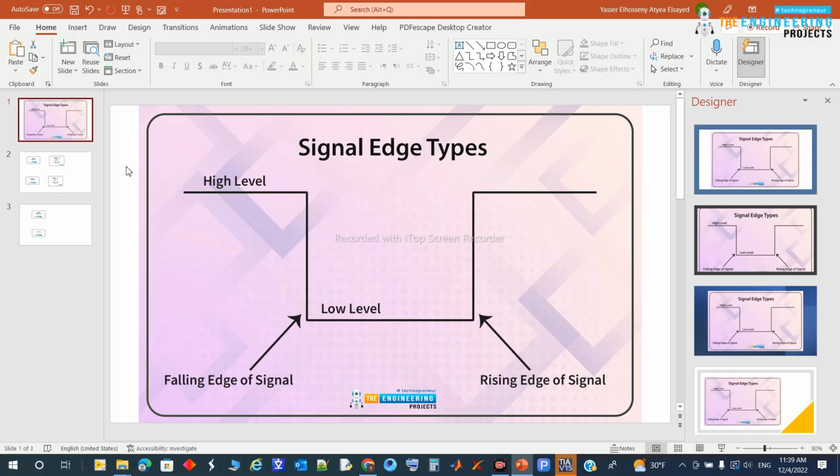Above 100 centimeters it will stop the pump, and before 100 centimeters it will start the pump to continue filling the tank. So this will happen by recognizing the transition from high to low or from low to high of the level switch signal itself.